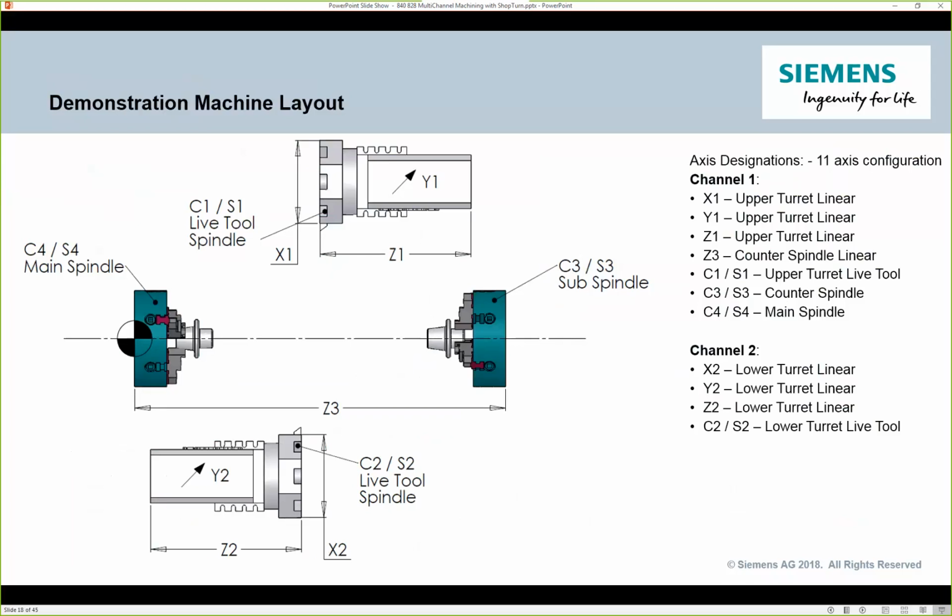Well, since the Z axis, the Z3, happens to be actually in the same assigned channel as Z1, when I program it, I must refer to Z3. Because if I just called it Z, the system wouldn't know which Z axis I'm talking about. So if you're bouncing between channels and you have 2 X's in each of the 2 channels, you don't have to worry about all these different terminology as far as which X axis I'm telling you. You would just call it the X of that channel. It's only when you have multiple axes in the same channel that we have to have a differentiator.